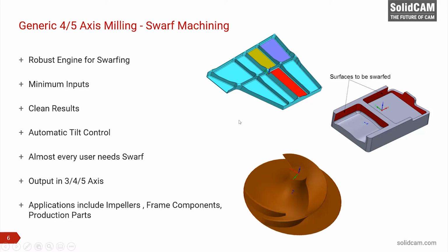Or frame components like this, where you would like to finish the walls using the side of the tool, single pass or a couple of passes. Or production parts where the walls are straight or having a draft and you would like to just finish them in one go.